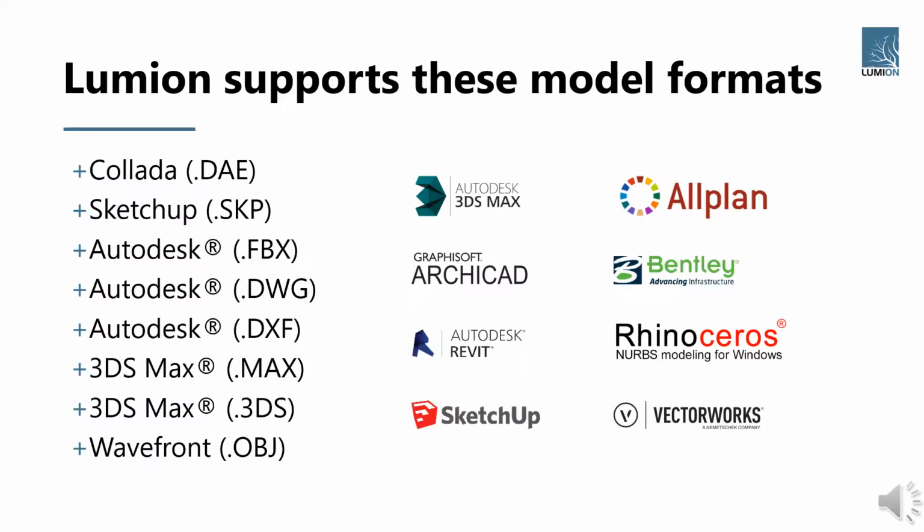Lumion can work with a select number of model formats. SketchUp has its own native format, and then Autodesk solutions have DWG, FBX or DXF, and 3ds Max can also load straight in as long as you have a copy of 3ds Max installed. If not, OBJ is a very typical format, as well as various solutions such as ArchiCAD and Revit have the ability to export Collada files via the LiveSync tool.